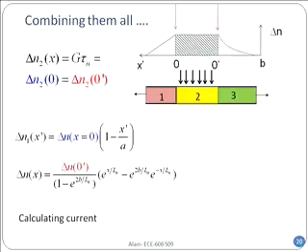Okay, now do you see it looks like some sort of bridge in the middle, but look, this is the carrier concentration. In the middle, uniform light shining. So what is the value of delta n in the middle section? G multiplied by tau sub n, right? At a certain rate it is being created and it's recombining at the same rate. And so steady state is G tau sub n. And on the left hand side, trap free, going to the metal contact, it is getting linearly to 0. So that's one side. The other side is full of traps and therefore it is disappearing faster, and therefore before getting to the contact.